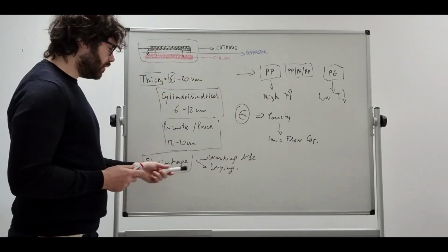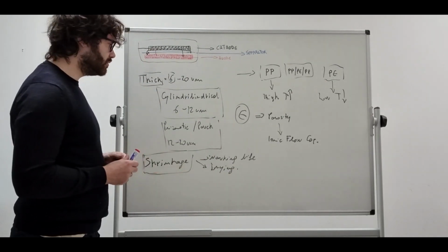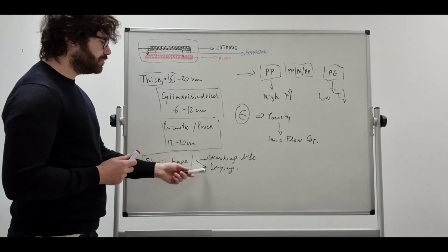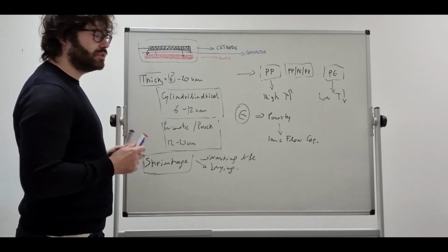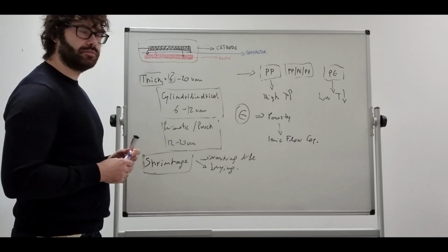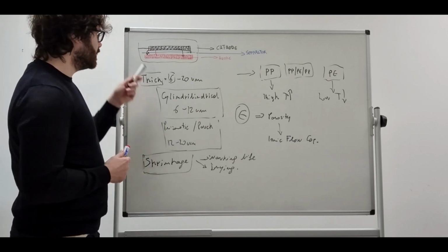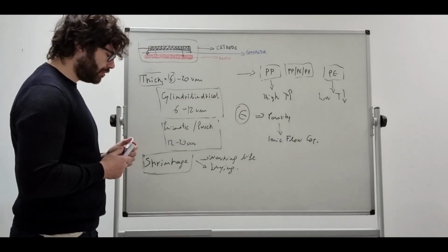As you know, one of the manufacturing processes foresees the drying of the cell or of the separator, and during this drying process at very high temperature, about 60 to 80 degrees, if the separator presents some shrinkage, it can uncover the cathode and then trigger some short circuit. Okay.